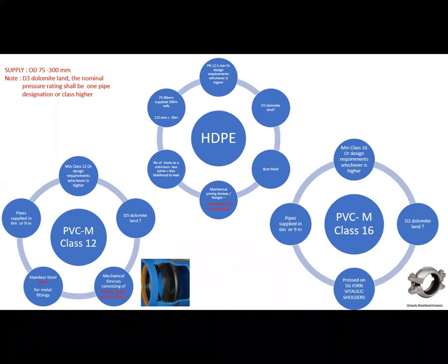And my understanding is that with these Victaulic shoulders, because there's a rubber ring on the inside, it does allow for a little bit of movement, which is probably needed if you're underground in an area where there is this leaching and a bit of movement. So I hope that picture gives you a little bit of an easier overview of table 5. I really hope that you can see that the importance of no leaks and quality plumbing is key.